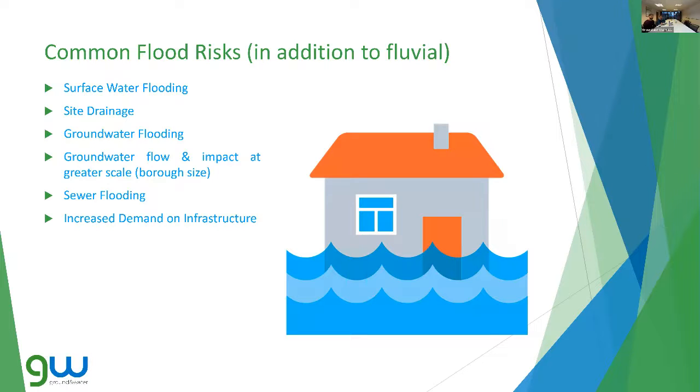Common flood risks: in addition to fluvial flooding from rivers and seas, obviously you have your flood defenses. Basements are underground structures, so we have to consider surface water flooding, sewer drainage, groundwater flooding, and this is another hot topic which is emerging right now.